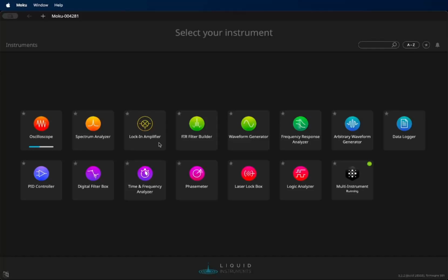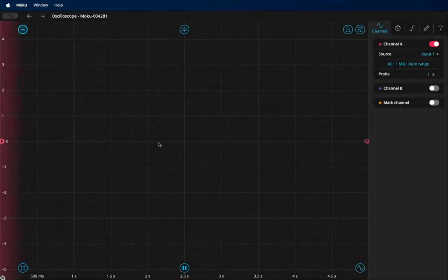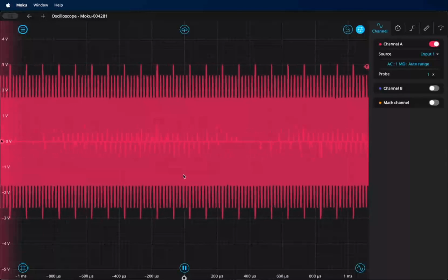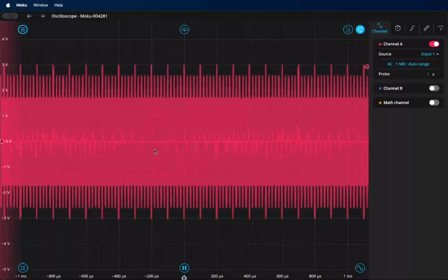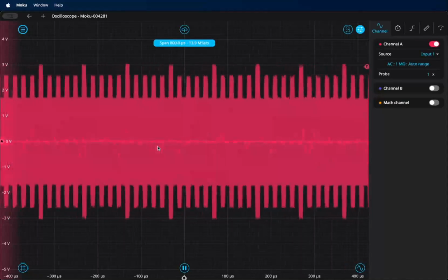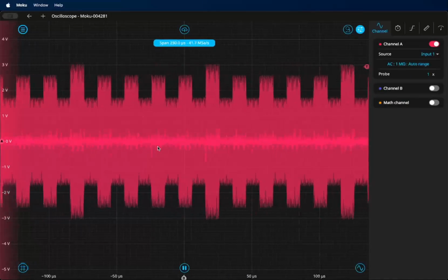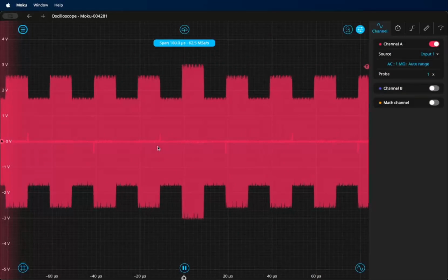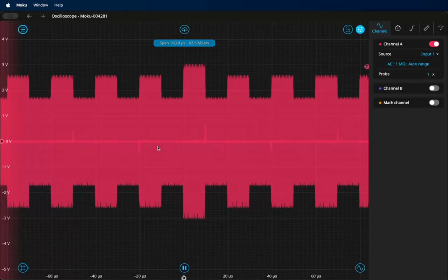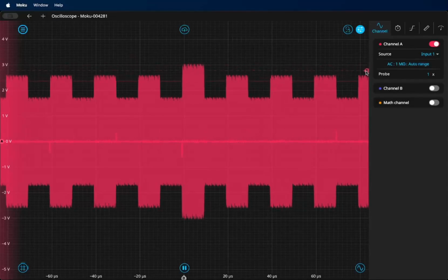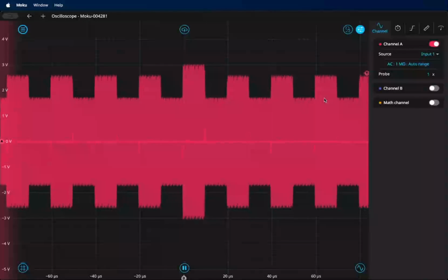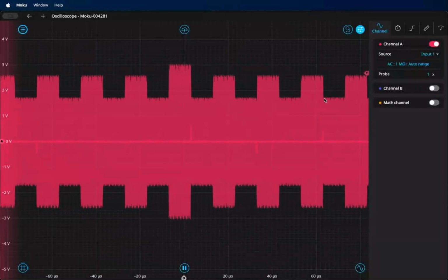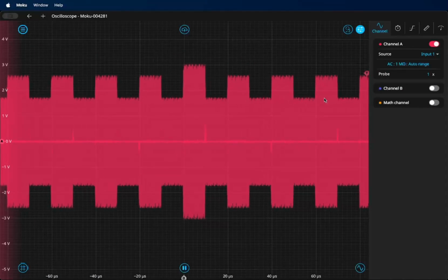Wait a second for it to configure. We're only going to look at channel A in this case. If you zoom out to about a 150 nanosecond window, and set the trigger level to where the highest signal is, you can clearly see there are three different bit values that we programmed into the pulse sequence. You can revisit the first video if you want to see those again.